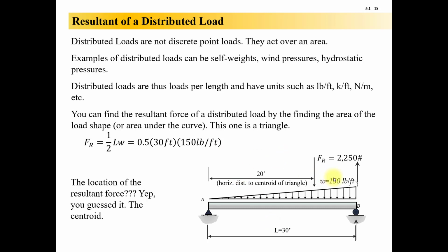Yeah, it was. All right, well, this is a triangle. So imagine this, instead of being, maybe the beam's getting wider linearly as we're going along, so the weight's getting bigger and bigger and bigger. Or maybe this isn't the self-weight. Maybe this is like, we've got one book stacked for the first foot, and then 2 books on the second foot, and 3 books on the third foot, 4 books on the fourth foot. You see how it goes. And so the weight that the beam is being loaded with here is increasing.